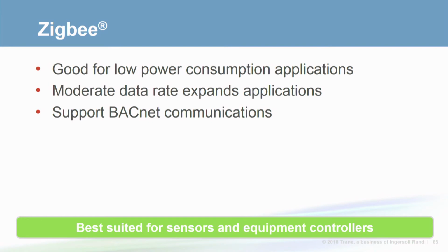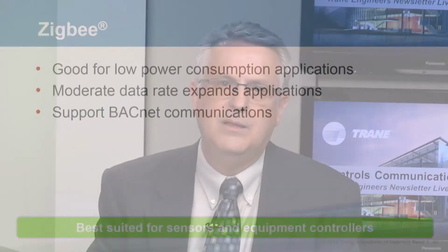Its low power consumption has made over a 15-year battery life possible on temperature, humidity, occupancy, and even CO2 sensing. Trane's analysis and experience has demonstrated that Zigbee can be a single solution for tools, sensors, equipment controllers, and for communication up to the building controller. The advantage of a single solution is that it simplifies and reduces the cost of installation while reducing wireless traffic.